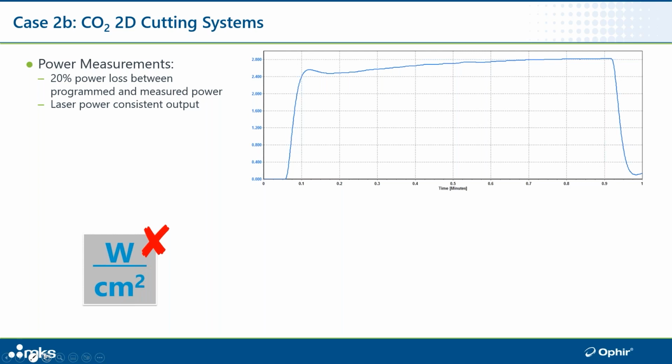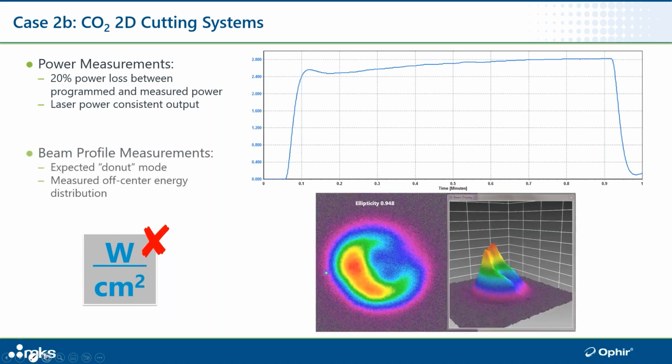In this case, probably what was happening is there was a consistent drop in laser power, and you see what operators do. They want to keep making good, consistent parts. So what will they do? They'll just continue to ramp up the power until it eventually reaches a point where you simply can't do that anymore, and you've got some real problems on your hands when you continue to operate the laser like that.